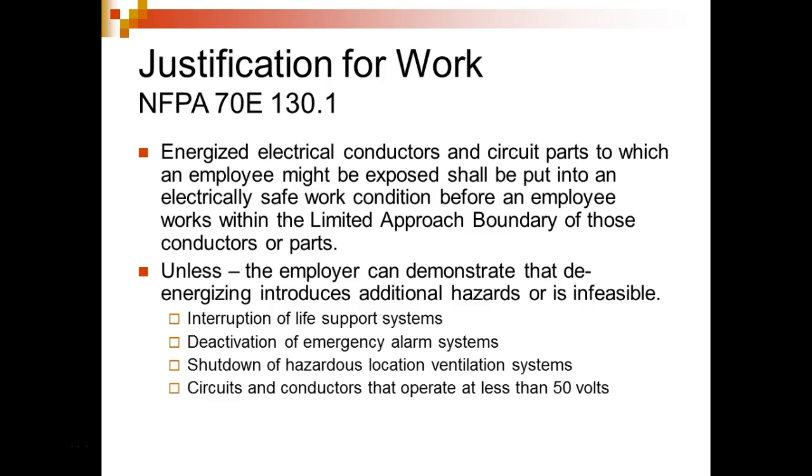So we don't have to make the circuit electrically safe, according to 70E, if it's at or below 50 volts. Does that mean 50 volts won't kill you? No. You still have to make sure that you're safe around those voltages. You have to understand when you hook up your meters and such, you still have to take those precautions and make sure you have it on the right scale. In EET 100, we blow fuses in meters all the time.